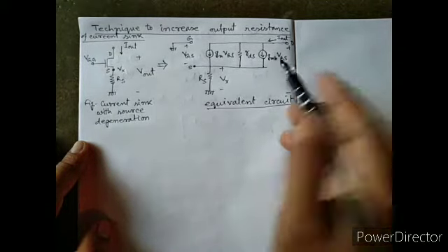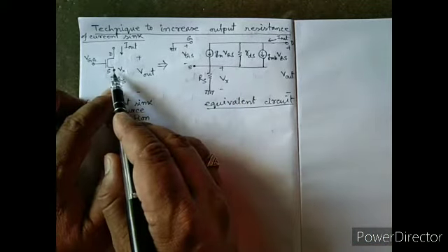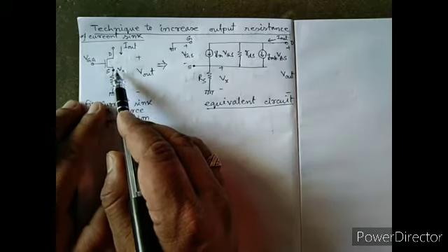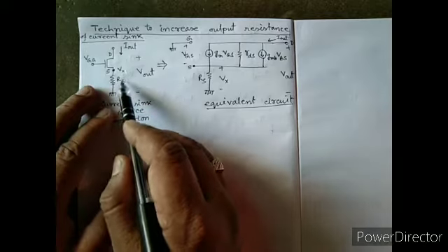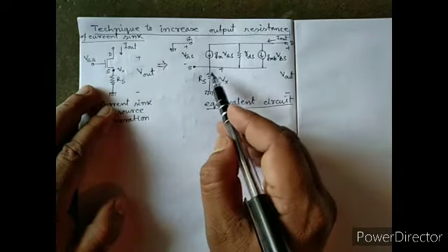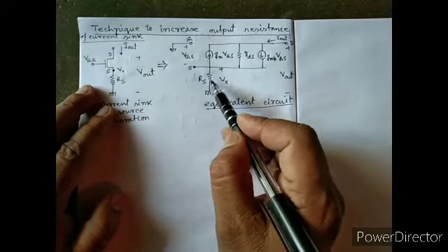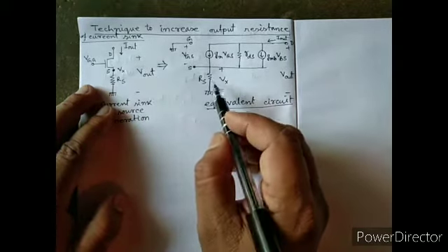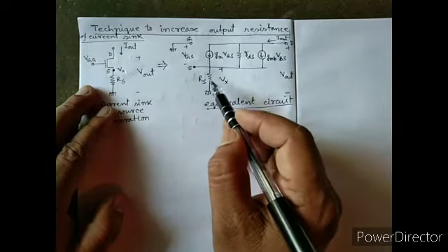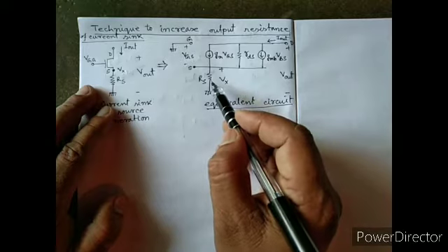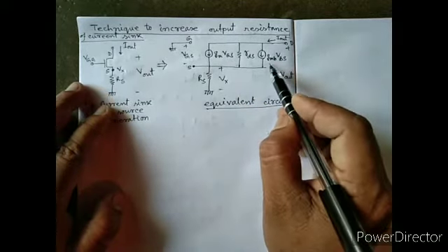What about this part? When there is a resistor at the source terminal, the source terminal is not directly connected to ground, so there is a potential drop across RS, which gives a potential across the body terminal. If we put a body bias, then due to body biasing the output current will change.